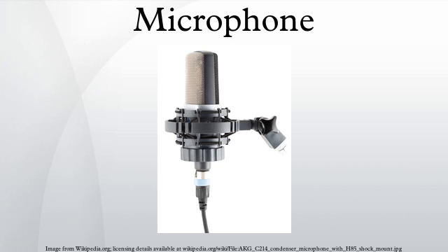A stereo microphone integrates two microphones in one unit to produce a stereophonic signal. A stereo microphone is often used for broadcast applications or field recording where it would be impractical to configure two separate condenser microphones in a classic XY configuration for stereophonic recording. Some such microphones have an adjustable angle of coverage between the two channels.